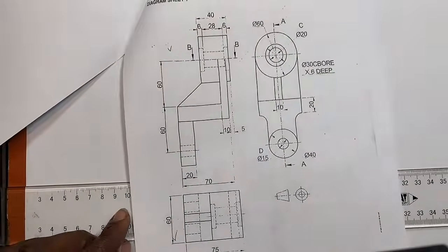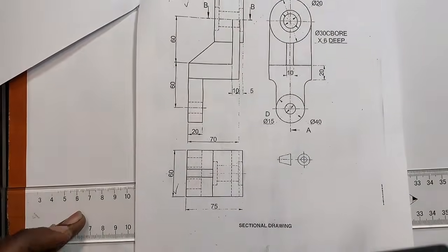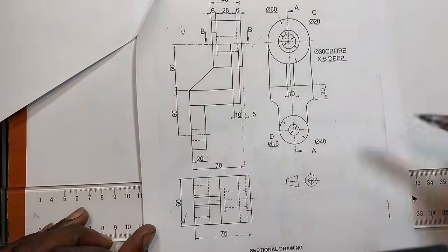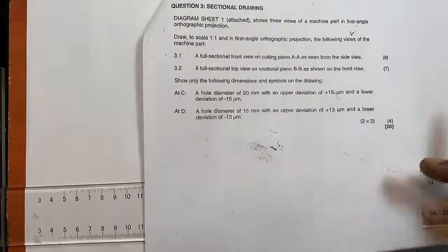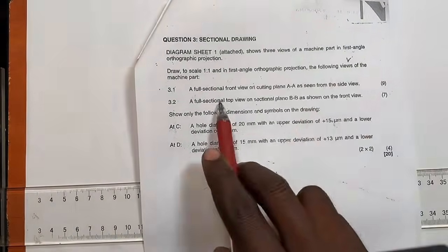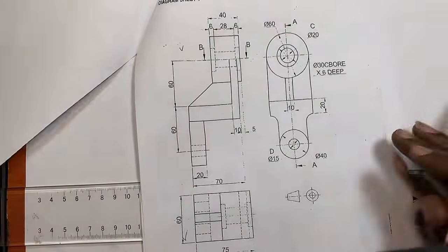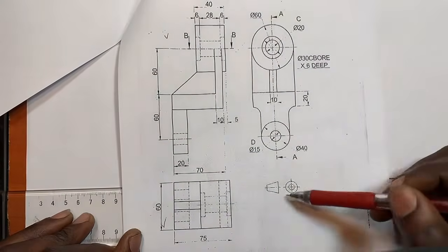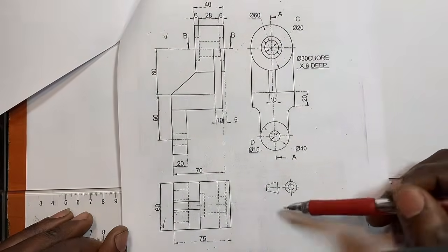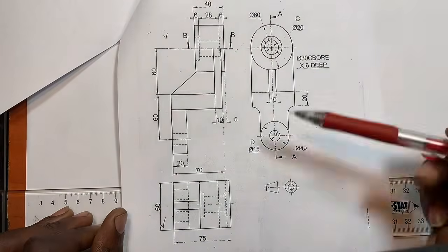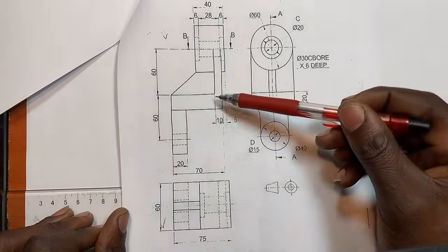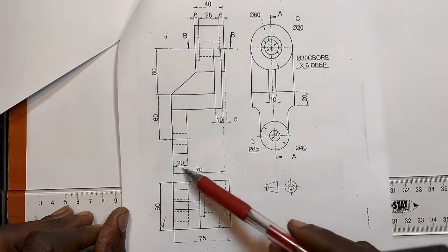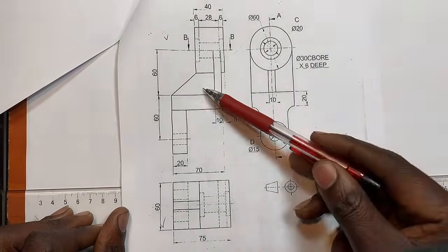You understand? So indeed they are given according to first angle orthographic projection, because sometimes again, like as I've said, the question might be like it's given in third, but the question said draw in first. So you can come back, you confirm that indeed they are given according to first, there is their symbol. You understand? So there is the symbol of first angle orthographic projection, which means that this is going to be your left, this is going to be your front, this is going to be your top. If you can just put a Cartesian plane here, first quadrant, second quadrant, third quadrant, fourth quadrant.